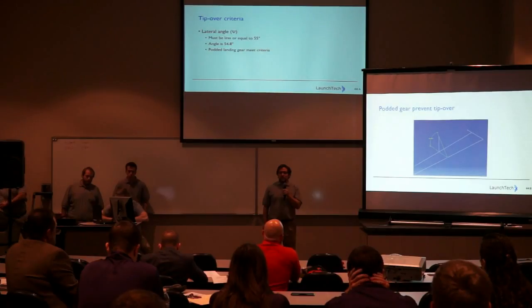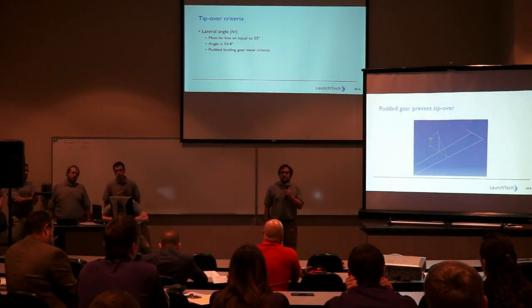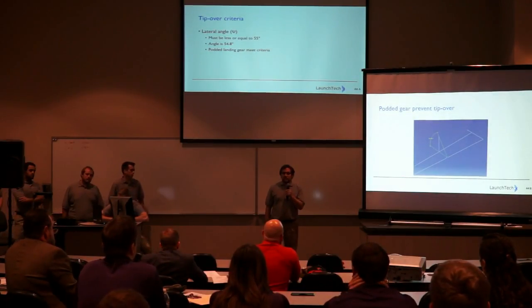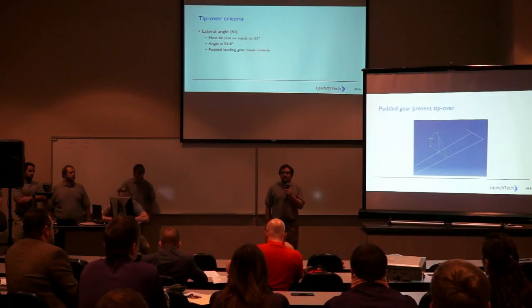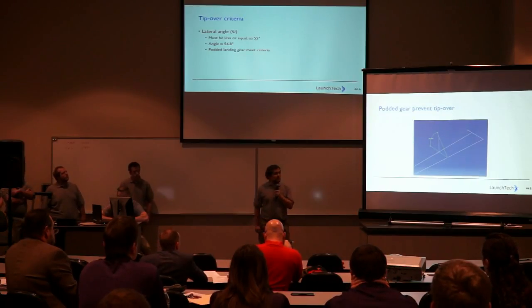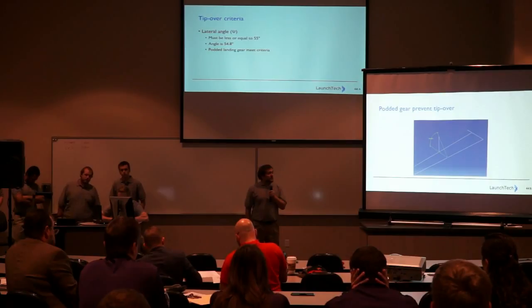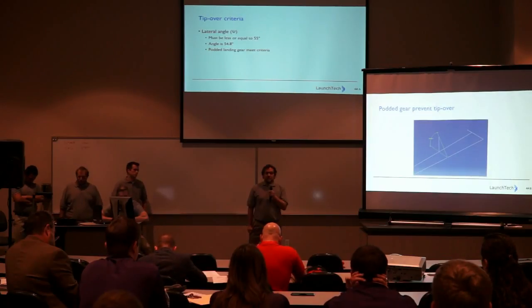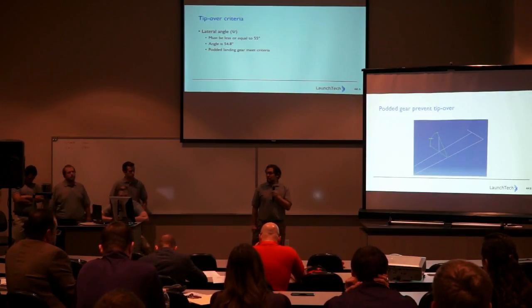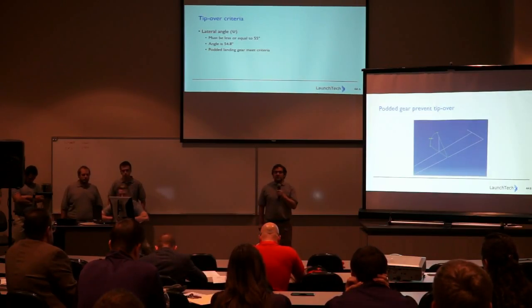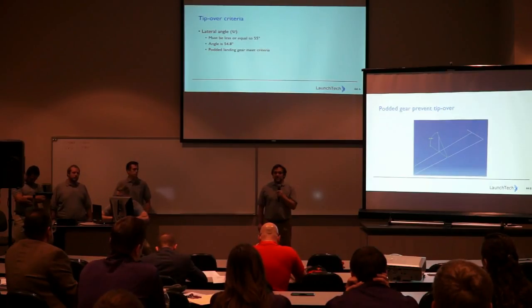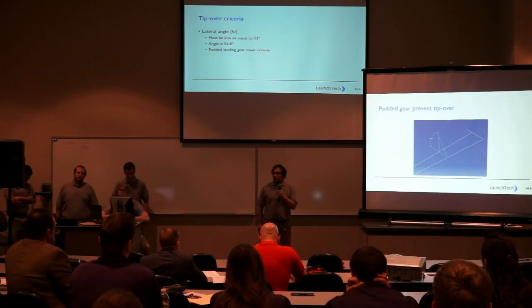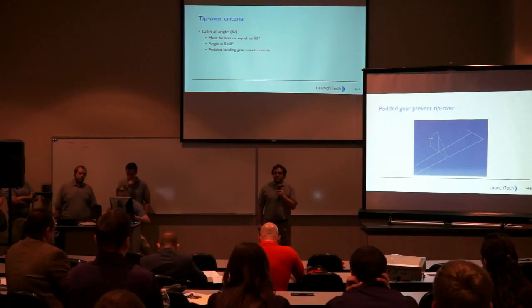For typical angle, in the lateral direction, the angle between the ZCG and the line between the front and rear gear needs to be at least 55 degrees. Shown on the secondary screen is the current model, estimating points in space for ZCG in both gear. For tip over, this needs to be under 55 degrees, and currently it is 54.8. This is achieved by placing the rear gear and pod and landing gear outside the fuselage of the aircraft.